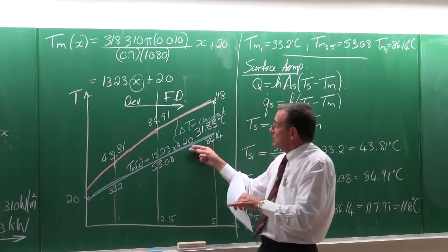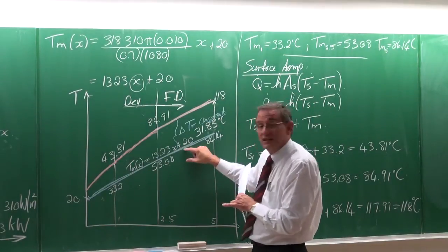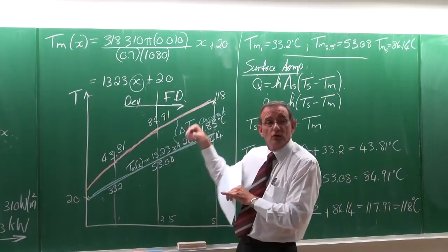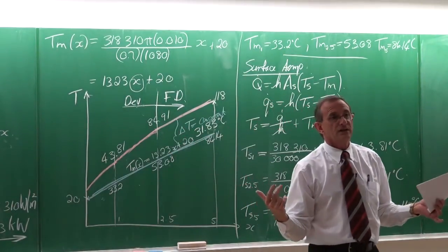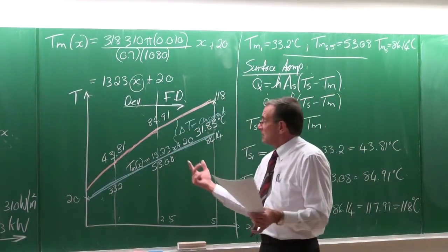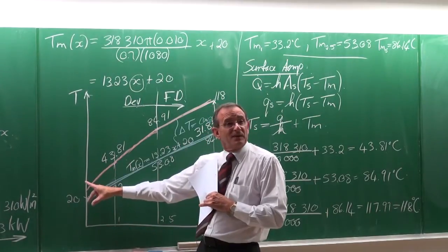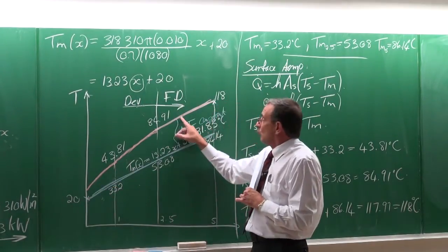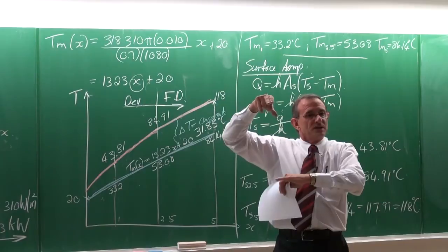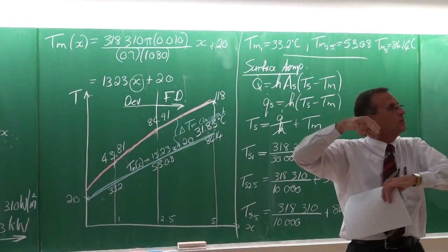Okay. Taking into consideration the heat transfer coefficients, that will be the surface temperature. Can't be anything different. If this inlet temperature increases with 10 degrees, then all those values are just going to increase with 10 degrees. So the delta T's will remain constant.